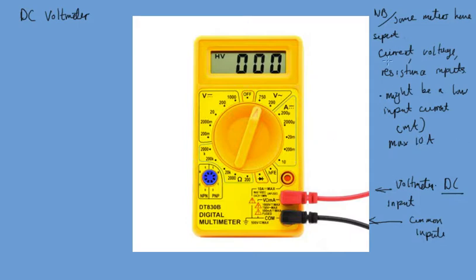So back to this, for our DC current, so we're thinking direct current and we're doing voltage. You've connected your cables, then we're going to select the highest DC voltmeter range. So this would be here. The highest one, that's millivolts here, where it's got the VM, so it'd be up to here, 1000. Unless you roughly know the voltage that you're going to get, then that would be redundant. You don't need to do that.